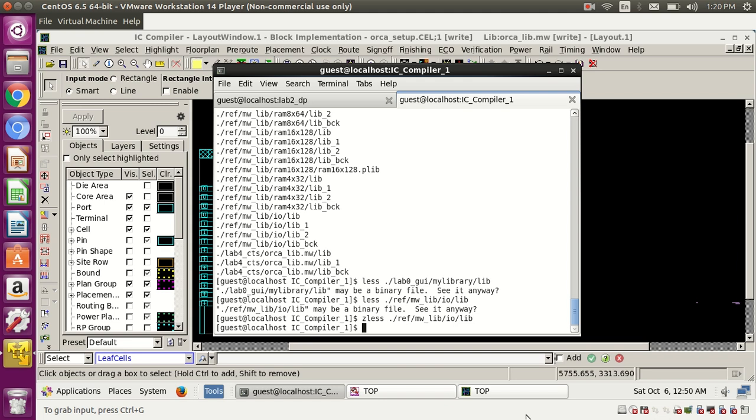Our actual clock should be, whenever you are giving one clock cycle to a flop, it should start, maintain the duty cycle, get off and go. So this complete cycle is the clock cycle. It is not that the low time can be more or less; that is the duty cycle. You need to maintain that duty cycle. I'll explain the duty cycle also. For now you have given the wrong clock, so setup and hold checks will fail for that flop. All the setup checks and hold checks are junk because we have given the wrong clock. So then the AND gate will not serve our logic.